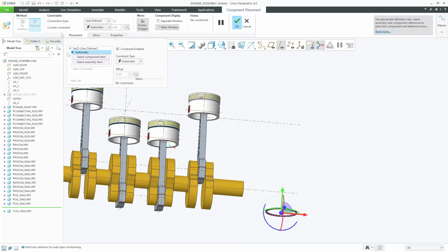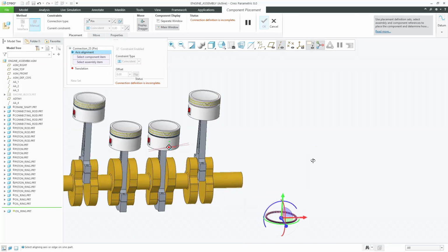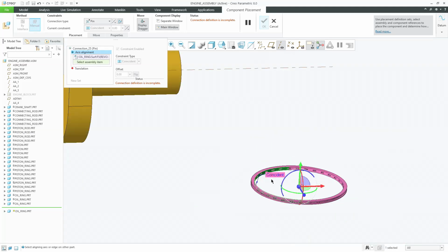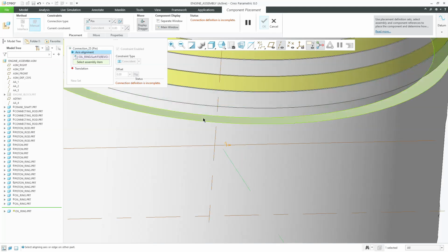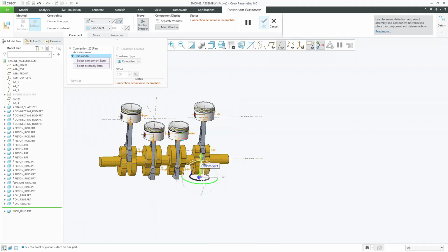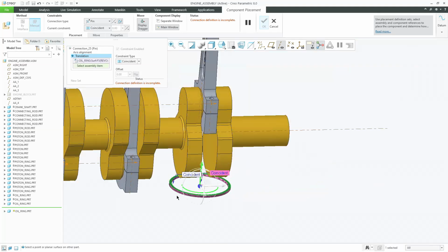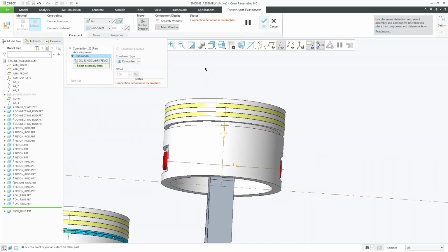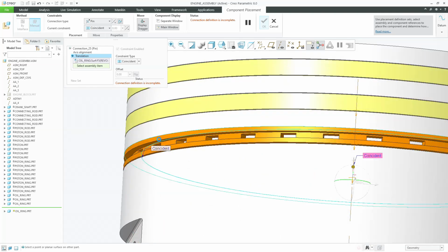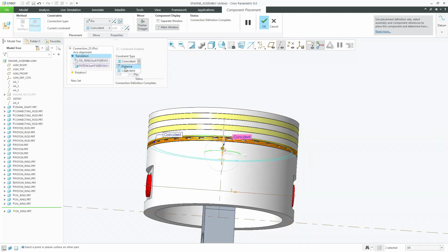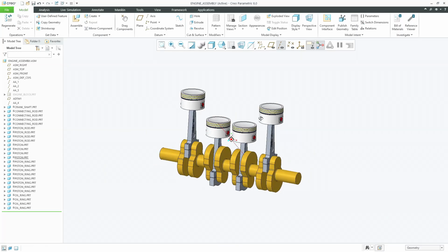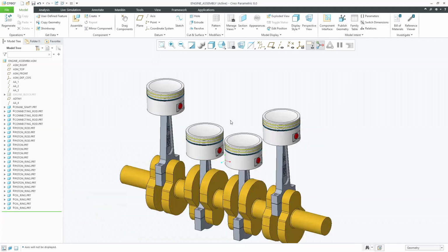of piston rings. Change it to pin connection, select the surface to the surface of piston, as well as select the top surface of the oil ring to the surface of oil ring area with a distance of 0.25 mm. So here we have connected all the piston rings and the oil rings applicable for this assembly. Next we are going to have an assembly connection between the piston to the engine block.